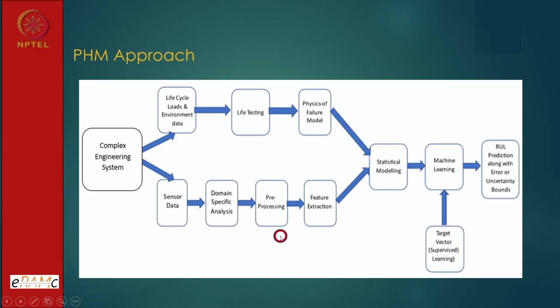And then, as I mentioned, pre-processing of information is very necessary. If we put the data in as it is, it will be difficult for the ANN to predict the remaining useful life. After that, extract the features: which frequency peaks, or what is their amplitude. If one is available and the other not available, what could be the reason? If both are available, their amplitude and the uncertainty in that.